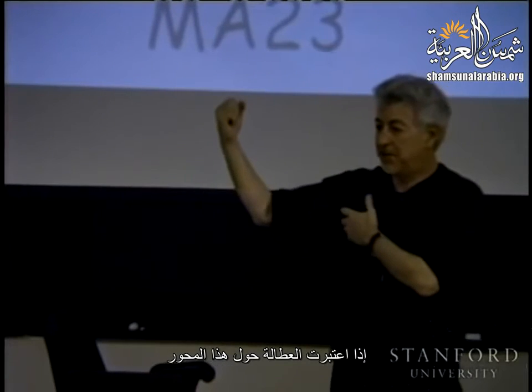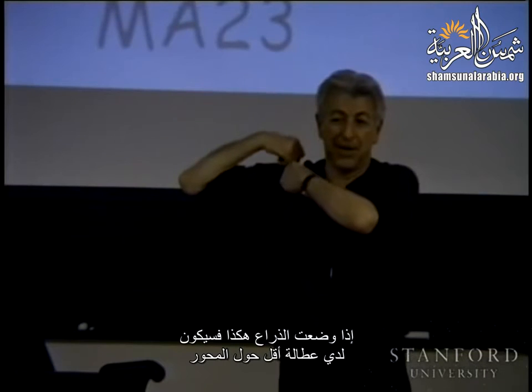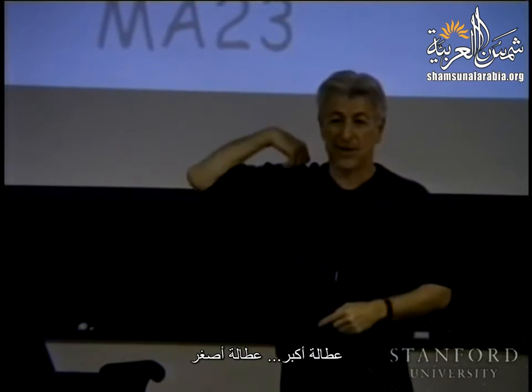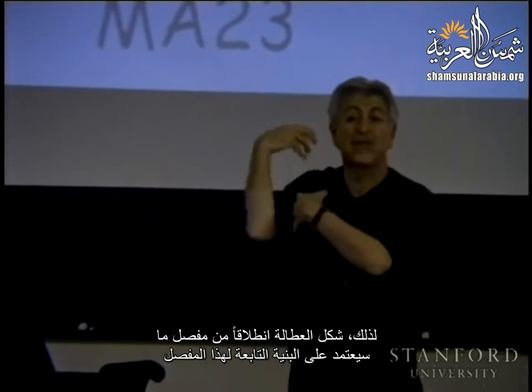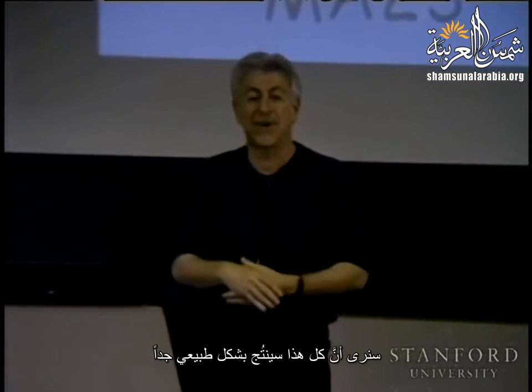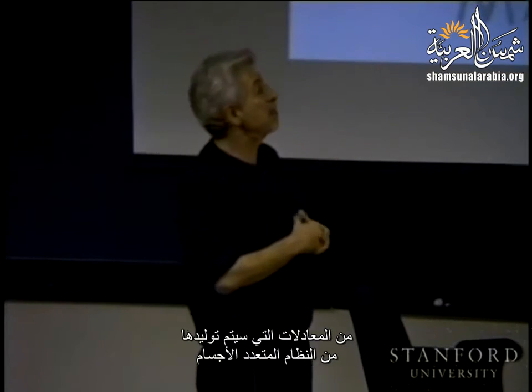So imagine if I'm considering the inertia about this axis. If I'm deploying the whole arm, the inertia will increase. If I'm putting the arm like this, I will have smaller inertia about this axis. Bigger inertia, smaller inertia. So the inertia seen from a joint is going to depend on the structure following that joint. And we will see that essentially all of this will come very naturally from the equations that will be generated from the multi-body system.